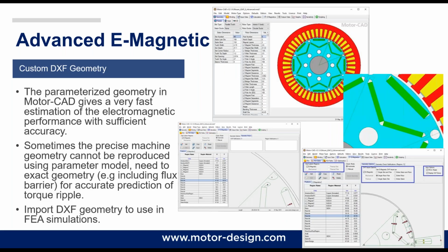So sometimes the user has to be very precise with the machine geometry, and it can be tricky to exactly reproduce the geometry by using the parameter model in MotorCAD. So sometimes it's needed to simulate the exact geometry, for example, including flux barriers, for an accurate prediction of torque ripple. So for this purpose, MotorCAD allows the import of DXF geometries to use in FEA simulations.